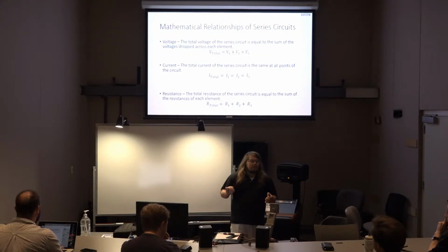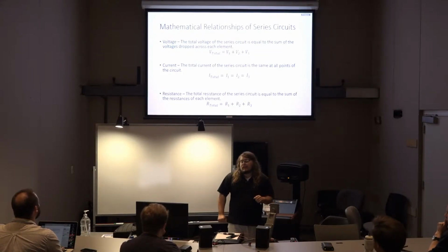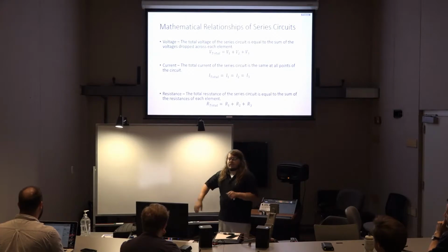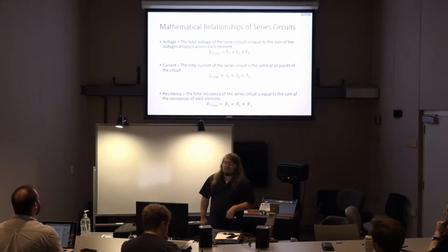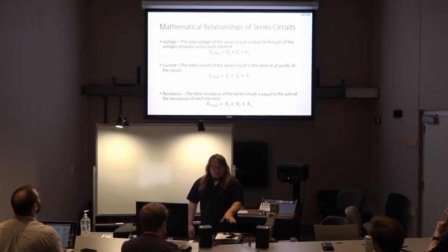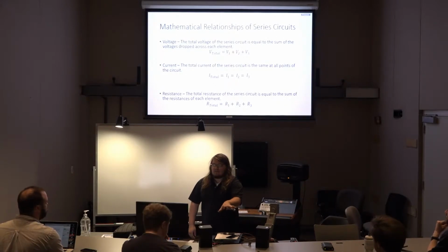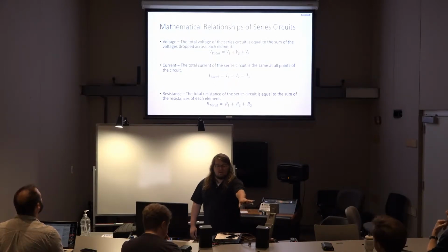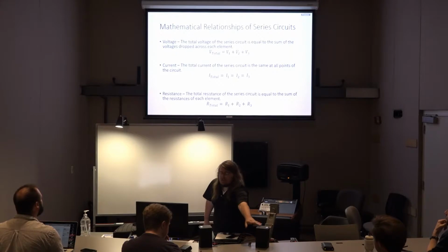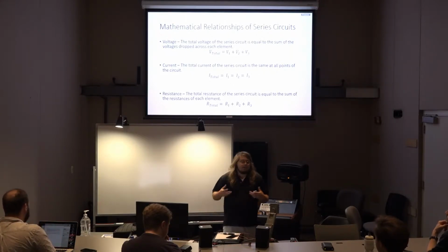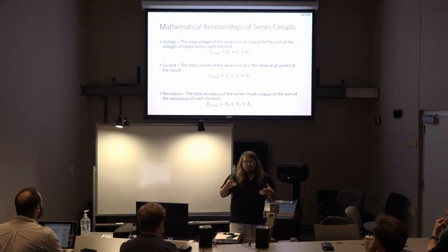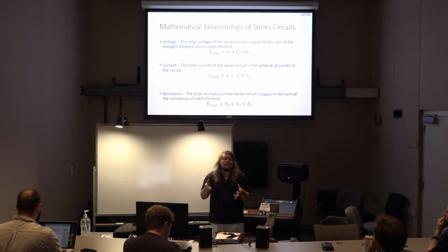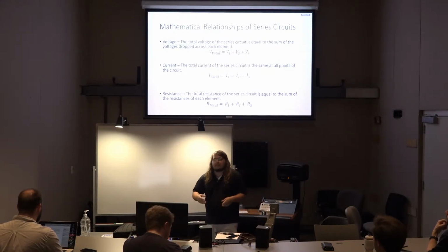Current in the series circuit versus the parallel circuit is a little bit of a sticking point. But if you think about it, we have a total resistance of the circuit, correct? We have a resistance of each speaker, they add together. That really forms what can be described as a single lumped element. You simplify the circuit.